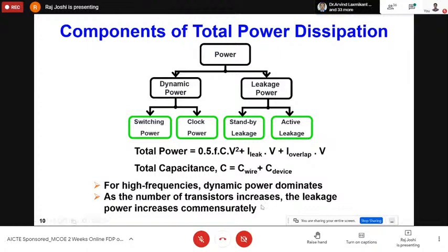As you know, as the number of transistors increases, the leakage power increases, not linearly, but even exponentially. Now in a processor, in all these chips, you'll find close to 15 to 20 billion transistors. The world population is only close to 8-9 billion. Now we are exceeding all those limits on the transistor level. That's great, but it creates a headache from a power perspective.